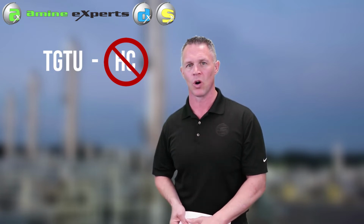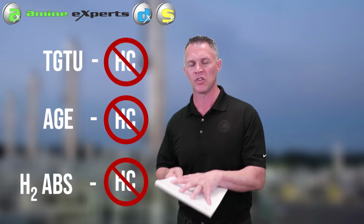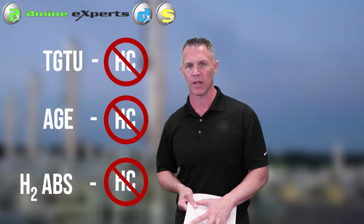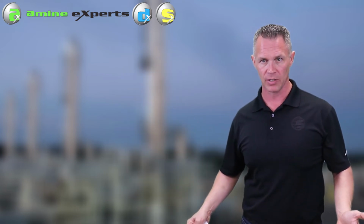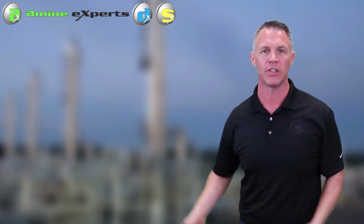Same applies for an acid gas enrichment absorber. Same applies for most hydrogen recycle absorbers. When you don't have these heavy gas phase hydrocarbons, you don't need to keep the amine warmer than the gas. But say you do have hydrocarbons, and so you do know that we need to keep a differential temperature. Well, now the question is, how much? Should it be 2 degrees, 3 degrees, 10 degrees?